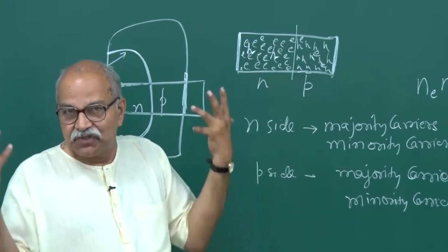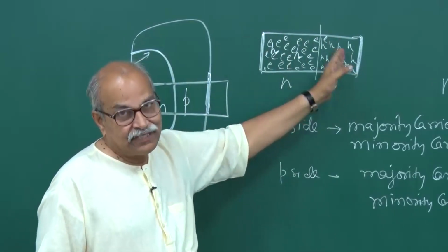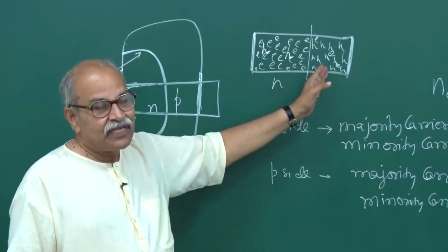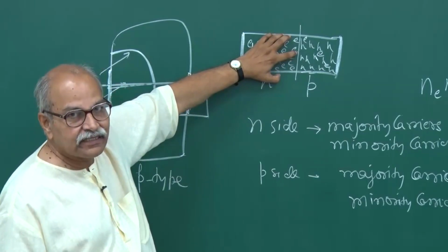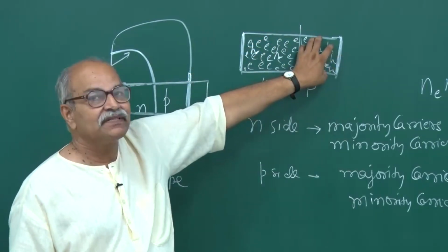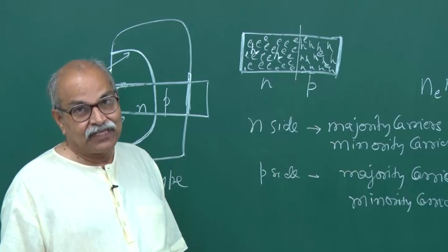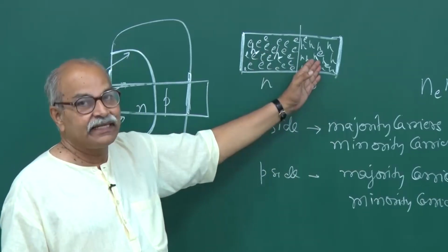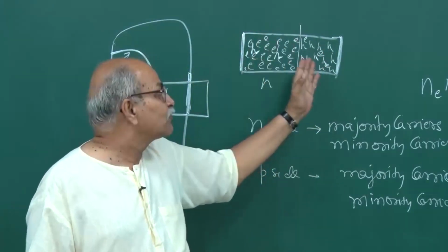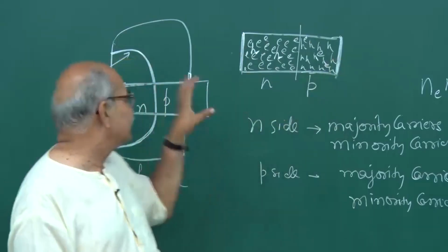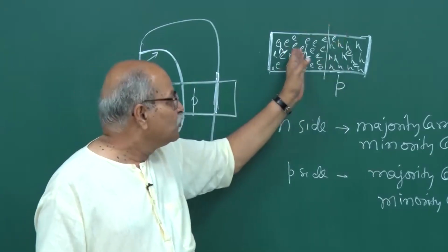So, all that usual electron movement and hole movement is allowed in this entire wafer, in this entire material. Therefore, having a large concentration of electrons here and a very small concentration of electrons here is a very non-equilibrium situation. If you have such a huge concentration gradient, and if the movement is allowed, they are allowed to go from here to here. Remember, the whole thing is one single crystal on which you have done all these diffusions, and therefore, that movement is allowed.